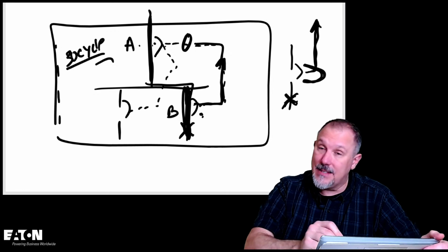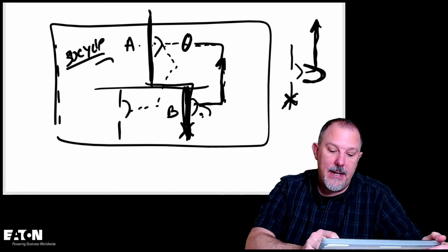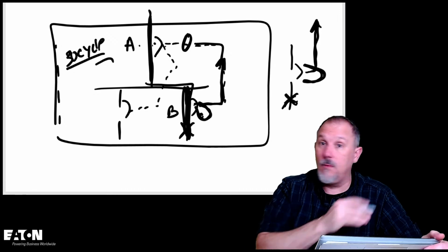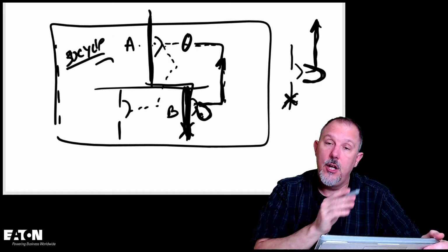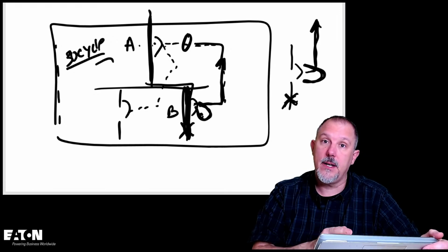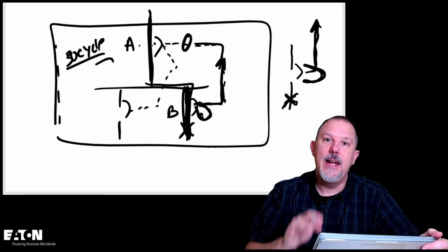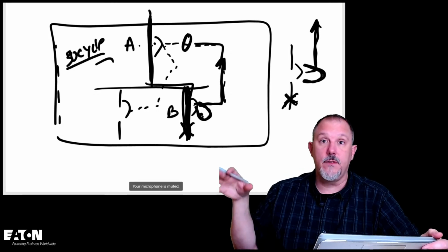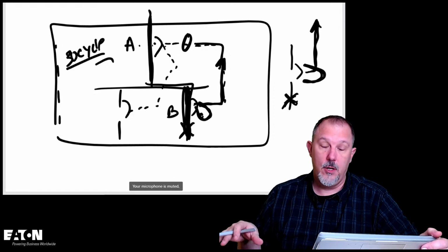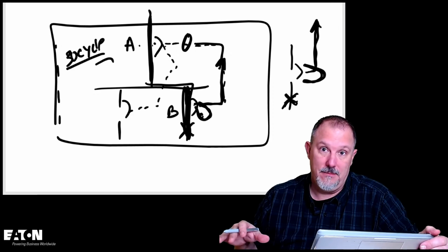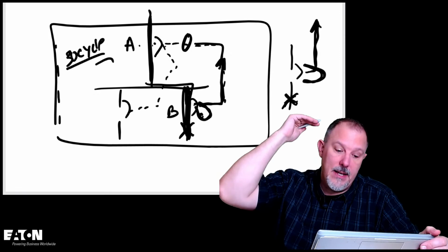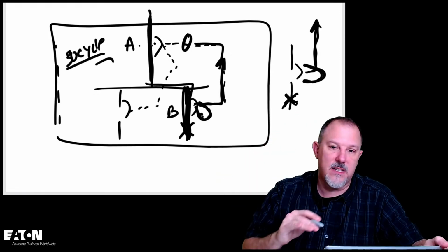And as it's the last device in the system, I jumper the last one, because if I didn't jumper it, as soon as it went above the short time delay pickup, it's going to trip instantaneously. And that would not be good for selectively coordinated systems or any level of coordination, right? Because then I could have my last device trip instantaneously.